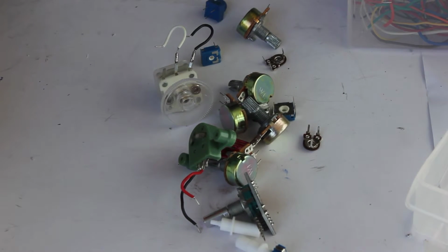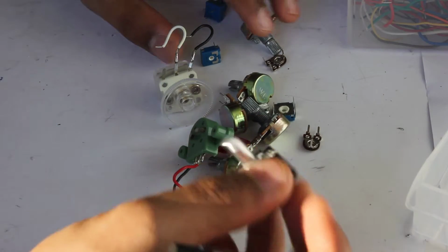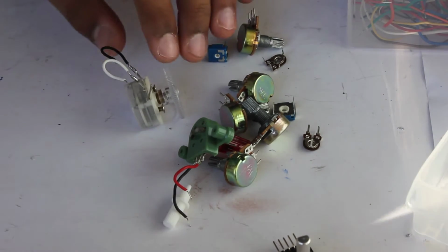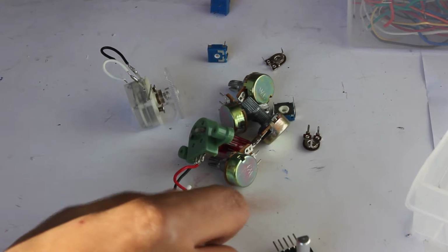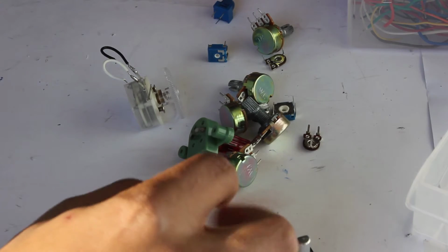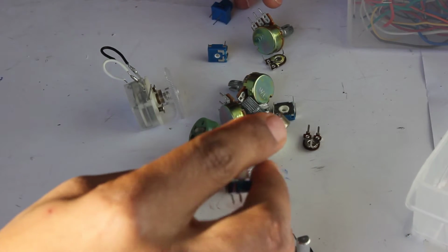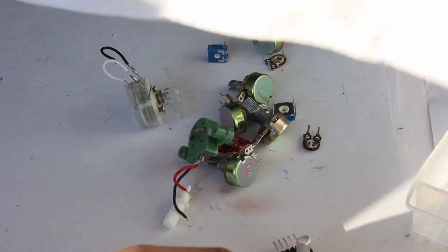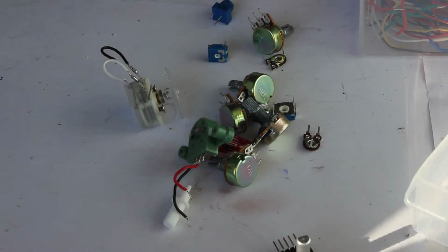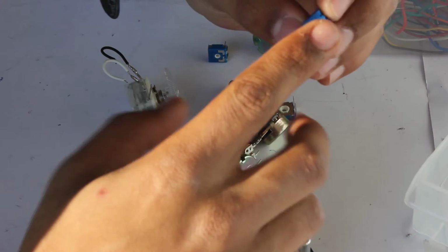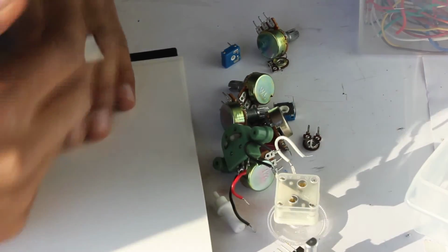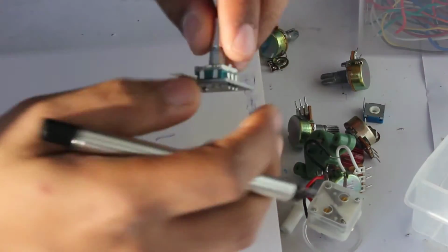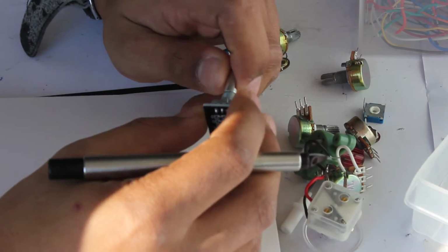Potentiometers. They come in all shapes and sizes. I have here many different potentiometers, all essentially do the same thing. Potentiometers are resistors, apart from you can vary them. So they're variable resistors, but they're not exactly like variable resistors. They have a slight difference. You'd expect a variable resistor to have 2 prongs. However, every single potentiometer you come across has 3 prongs. Why? With potentiometers, you have 3 prongs because each potentiometer gives 2 values of resistance at any given time.